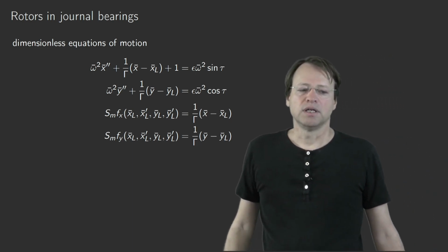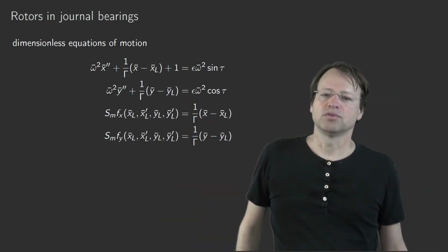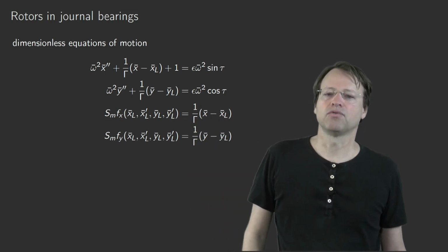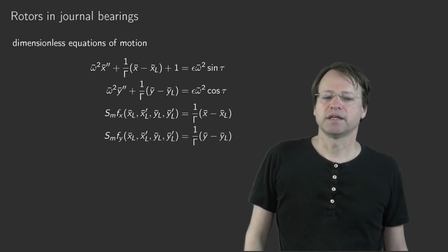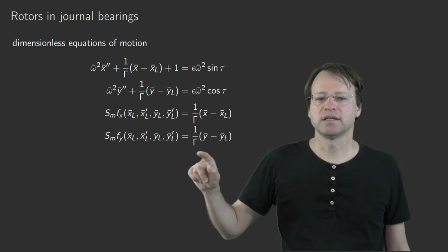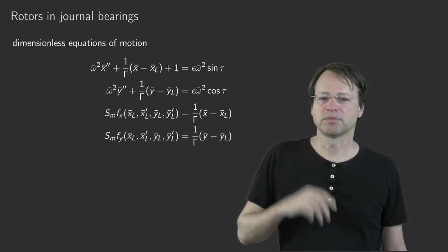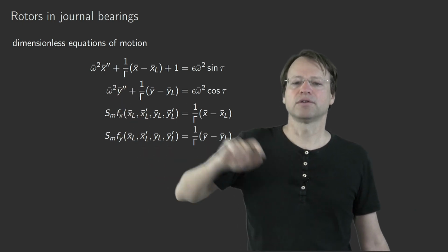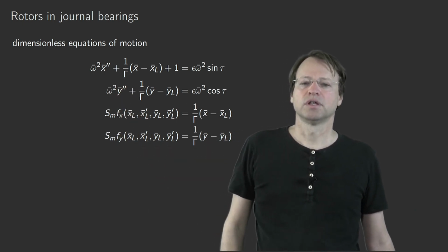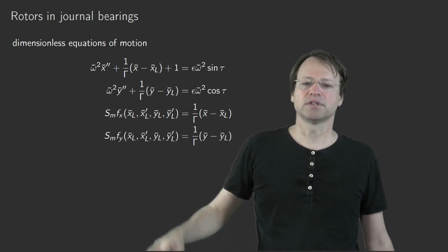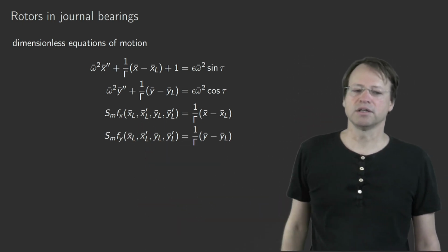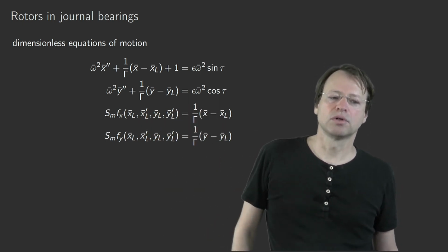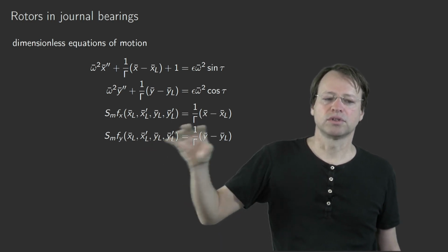So now let's write from this equation of motion by introduction of displacements, so of perturbations, delta x, delta y, and delta xl and delta yl, so 4 displacements. Let's write this in matrix form. Then we would have a diagonal matrix in the first two entries of the second derivative of the displacements. However, from the other two equations, we do not get any contributions. Then we would see the damping matrix in the last two rows. And the same holds for the stiffness matrix.